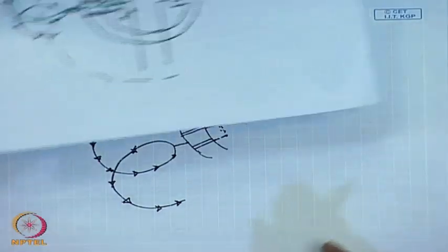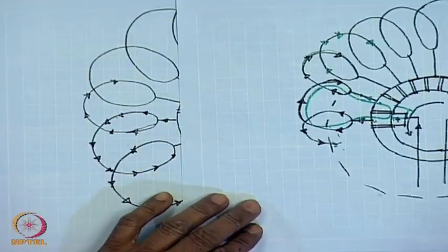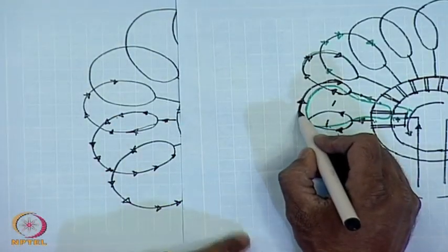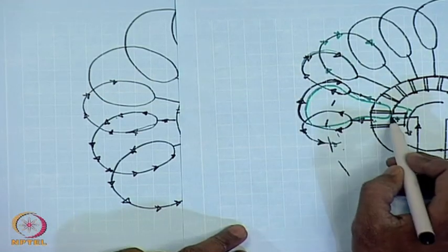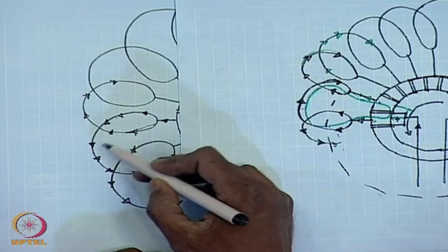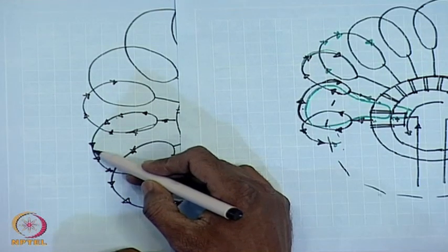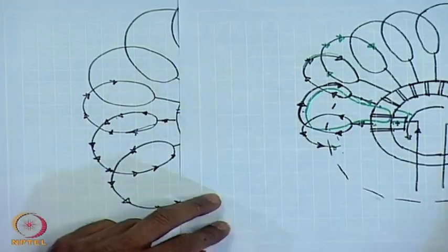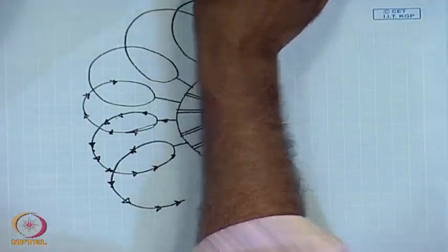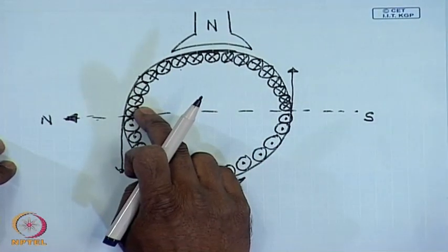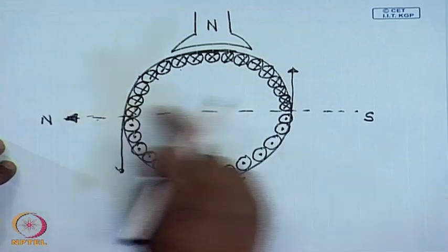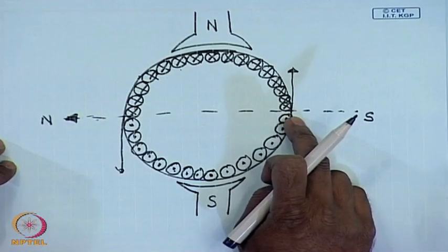Comparing the direction of these two coils, we see that the direction of the current that was shorted, which is said to have undergone commutation, has changed in that coil. Therefore, the coil in this picture that undergoes commutation, before commutation it had a dot current and the corresponding other side has a cross current and the corresponding side has a dot current.